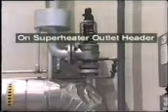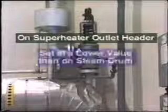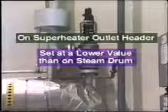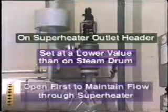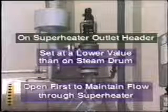Safety valves are located on the superheater outlet header. These safety valves are usually set at a lower value than those on the steam drum. And this is to make sure that the superheater safety valves open first and so maintain a flow of steam through the superheater. In addition to this, the setting must allow for the pressure drop through the superheater, which may be in the order of, say, 60 psi, 4 bar.